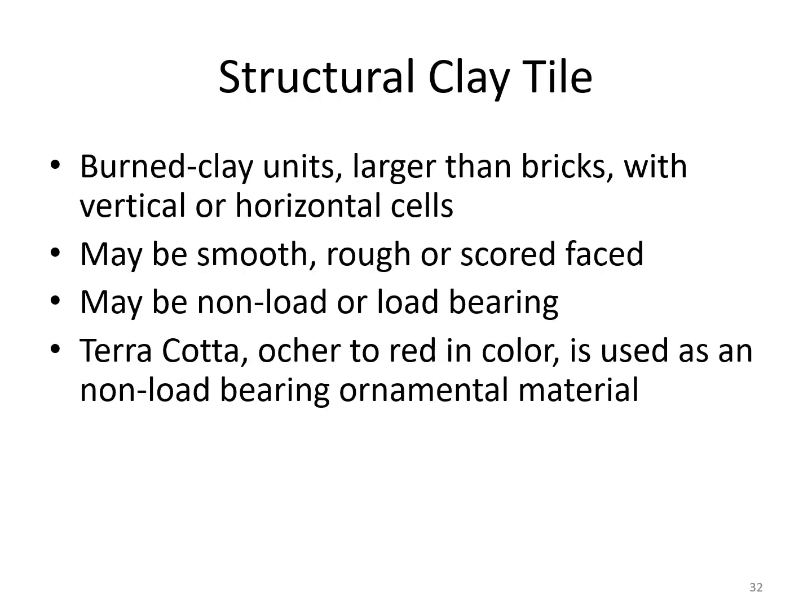So structural clay tile, this is another one. These are burned clay units. They're larger than bricks with vertical or horizontal cells. They can be smooth, roughed, or score-faced if you've ever seen them. The score-faced always sticks out in my mind. They may be load-bearing or non-load-bearing, and they're usually made of terracotta, ochre to red in color. They're very light because of being made of the terracotta.